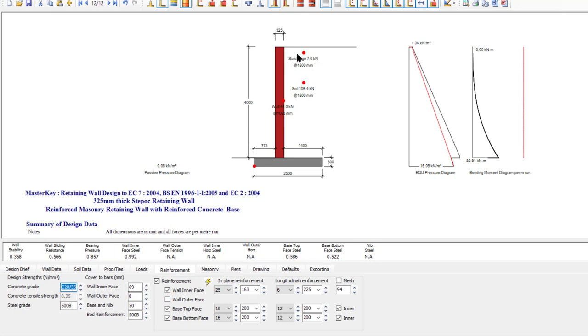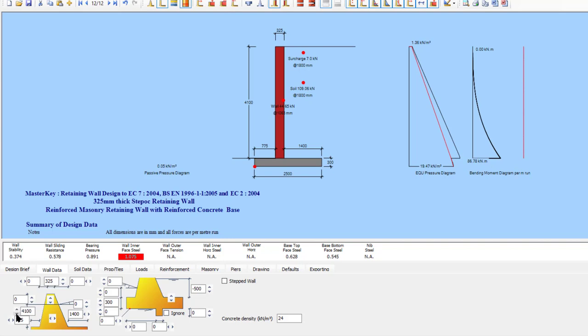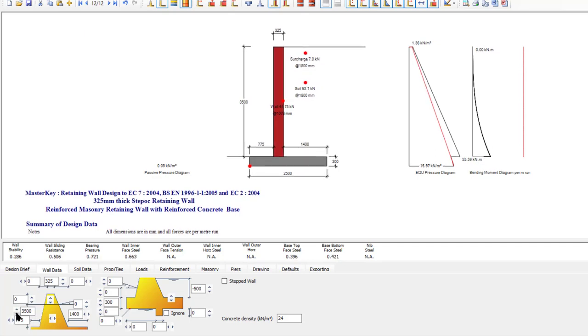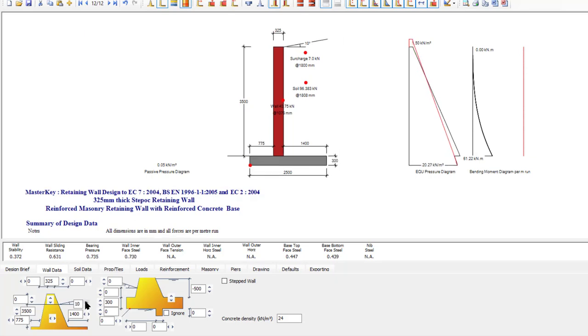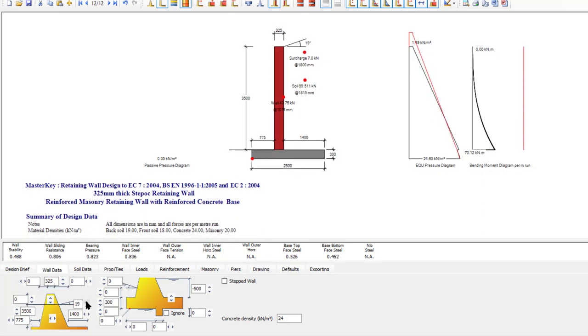So I can turn around and say, well, actually my wall is going to be 4.1. Well, maybe not. 4 is exactly the height you are allowed, but we'll take that down and say it's 3.5, but we're then going to slope up the back of the foundation. How many degrees can we afford to go before the wall would get annoyed? And it's reasonable, so we could go up to about 18-20 degrees and it would still be fine. So with the Steeppave you're nearly halfway there anyway, because we've pre-configured them to work, and you're just putting in a foundation base and go.